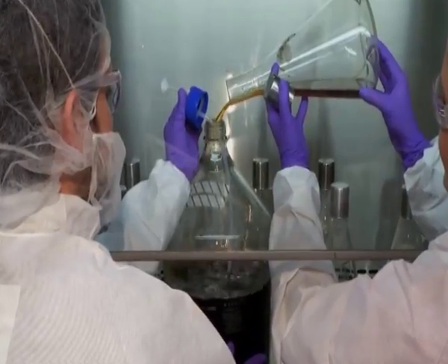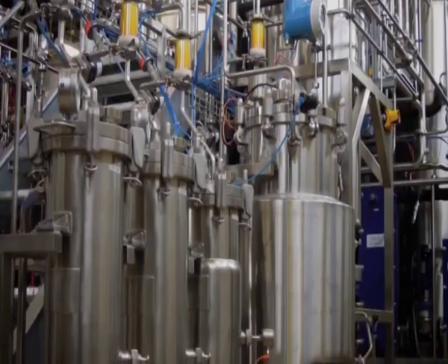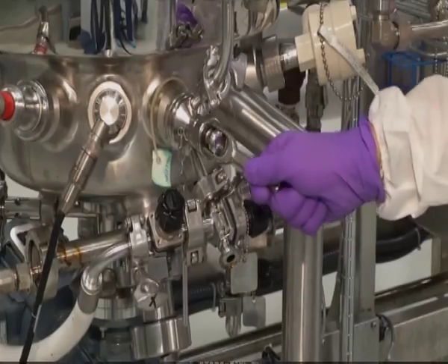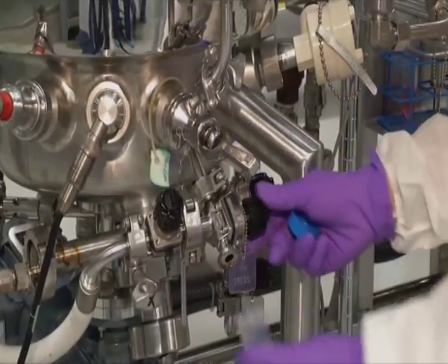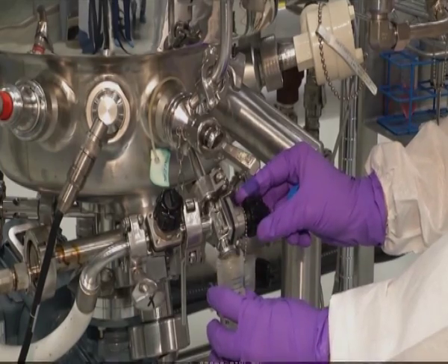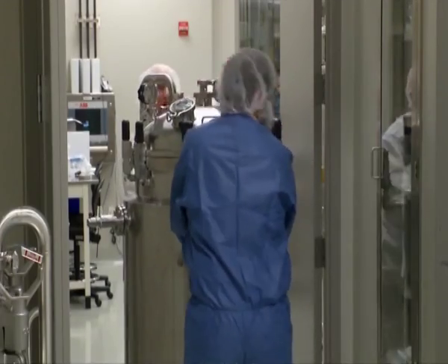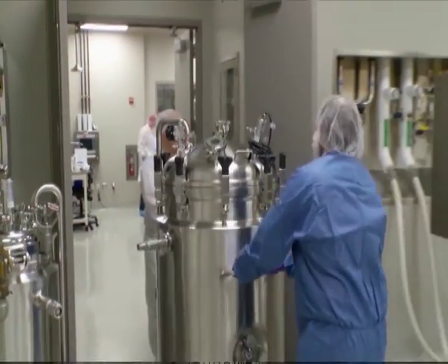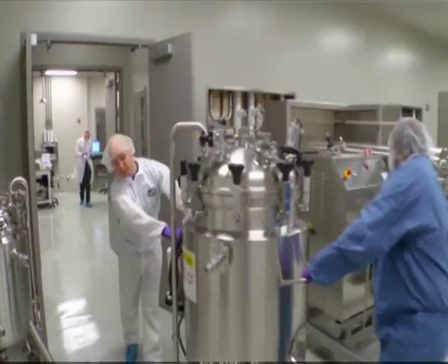To ensure good recovery or purification, speed of operation may be an overriding factor because of the labile nature of the product. The processing equipment must therefore be of the correct type and also the correct size to ensure that the harvested broth can be processed within a satisfactory time limit.